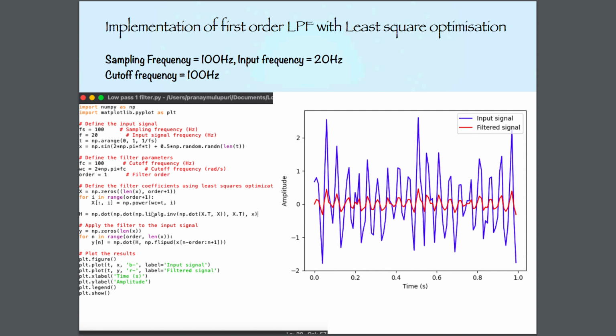The program will execute every point and check which point is getting nearer to the predicted values by taking all the optimal frequencies from the arrays. Then we are going to apply the filter to the input signal. So y is our output. For this order of the array which we have already created, we are finding the response of the filter.